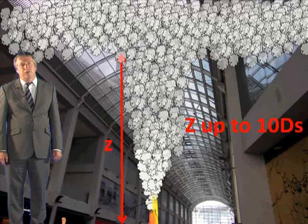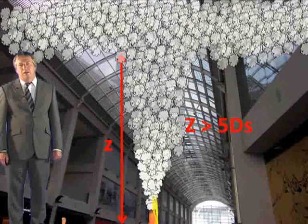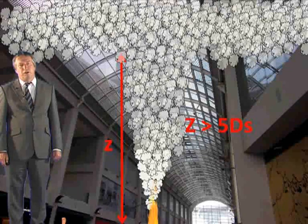Again, this is quite a large range and is probably appropriate for most fires in buildings. Also, this model is valid for heights of rise, that is clear layer heights, of up to about 10 times the maximum dimension of the fire. However, as we discussed earlier, it's possible to use the far field model for clear layer heights of around 5 times the maximum dimension of the source fire.